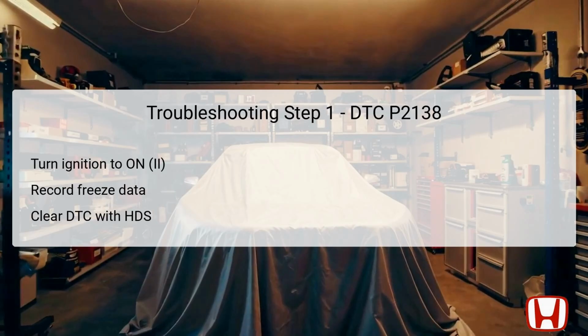The first troubleshooting step for addressing DTC P2138 involves preparing the vehicle and diagnostic equipment. Start by turning the ignition switch to the on position without starting the engine. This action powers up the vehicle's electrical systems and allows for data retrieval. It is essential to record all freeze data, which provides valuable insight into the vehicle's condition leading up to the error, including the speed, engine load, and other parameters.